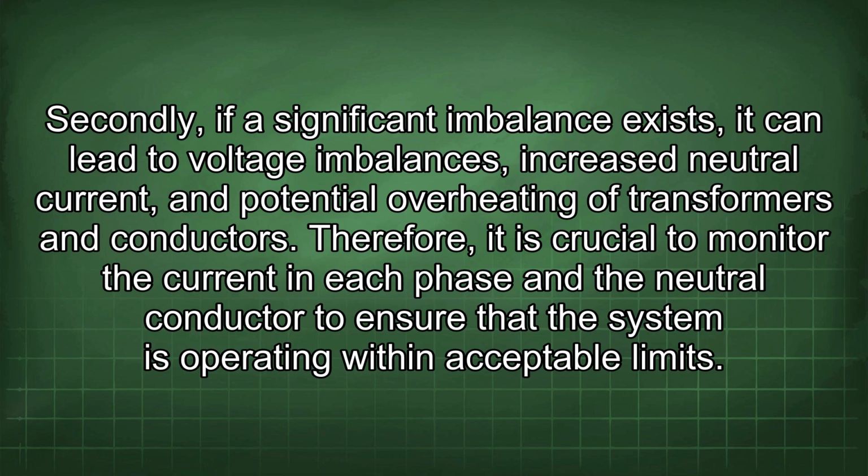Secondly, if a significant imbalance exists, it can lead to voltage imbalances, increased neutral current, and potential overheating of transformers and conductors. Therefore, it is crucial to monitor the current in each phase and the neutral conductor to ensure that the system is operating within acceptable limits.